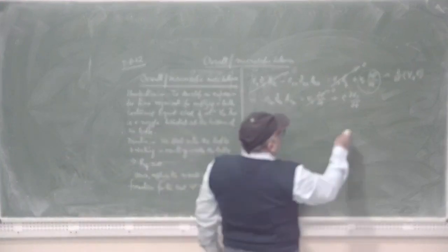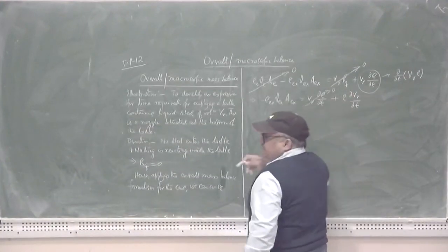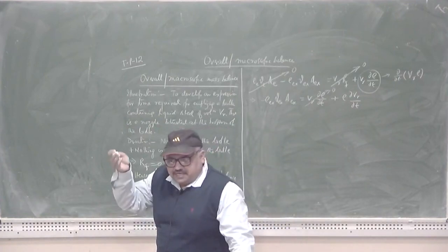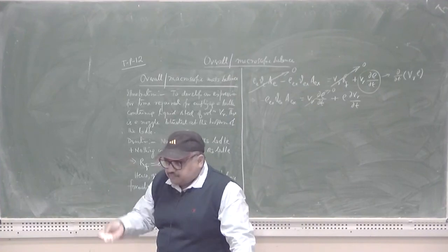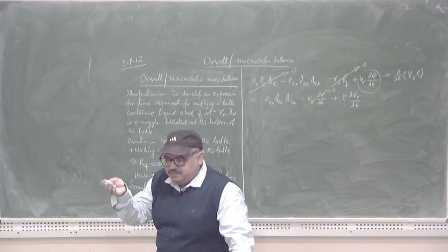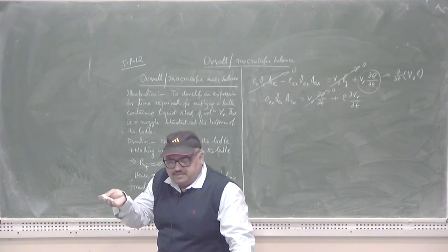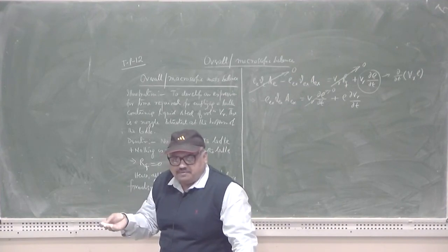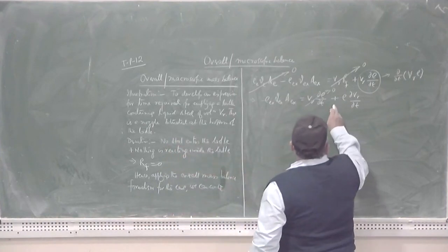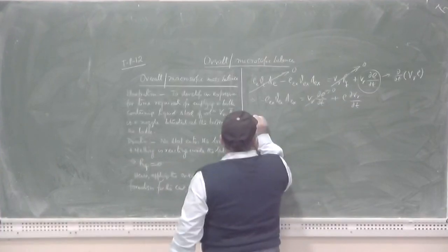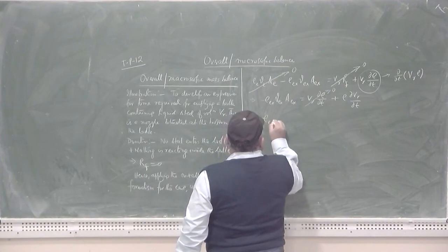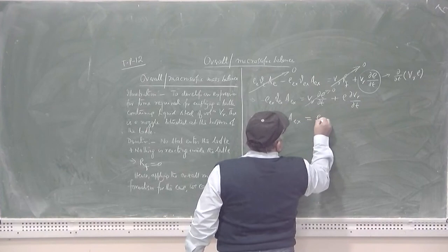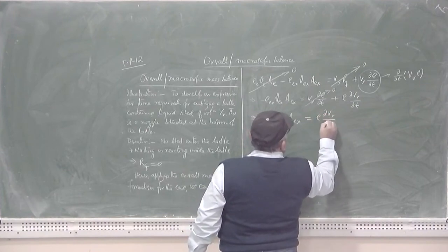The quantity which is changing is the quantity of the steel, because there is a continuous removal of the steel from the ladle to the atmosphere going on through the nozzle at the bottom. This quantity is 0. So, we can write minus rho_ex V_ex A_ex should be equal to rho d V_R by dt.